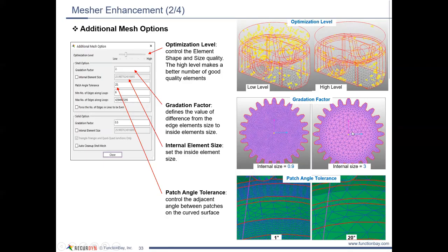Now we get this mesh with fewer elements, but as far as the results of working with this body, you can end up with fewer elements and still have the same accuracy in the results. That's something you want to try out and then compare results. Make sure you're not losing any quality.